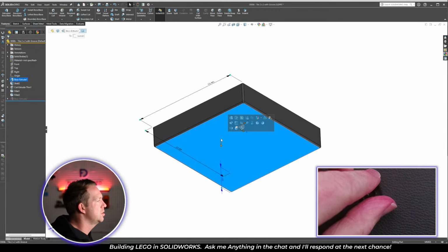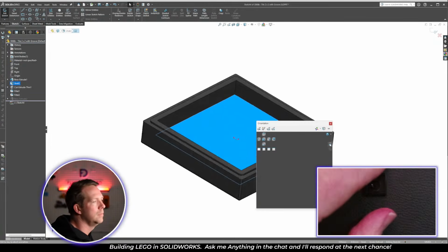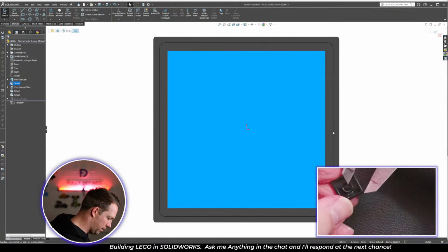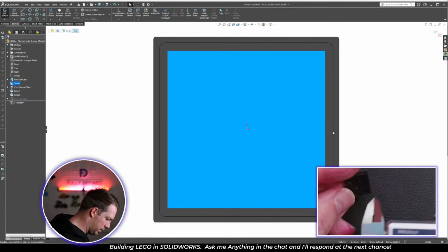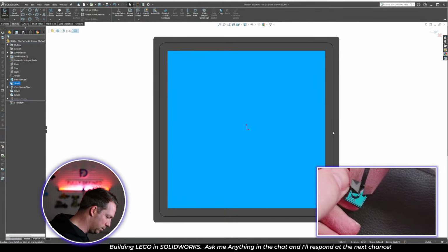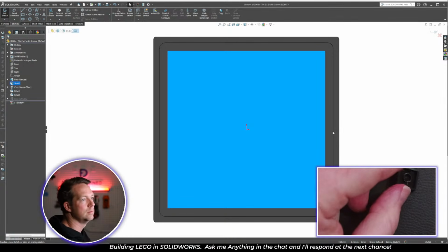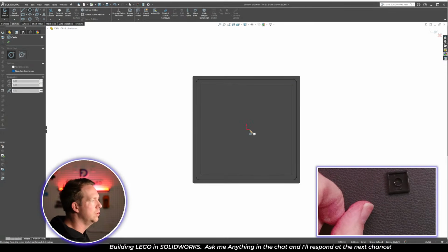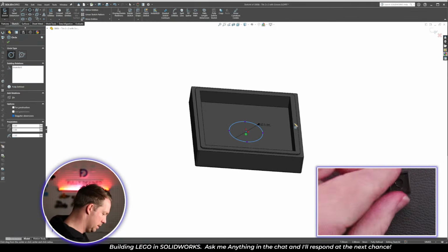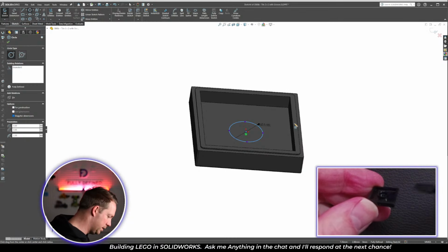So we can sketch on either face. Let's sketch on this face. And this should be something that we can dimension or measure pretty easily. So let's go inside of the circle. It's 5, and then thickness of the circle, 0.8. So we'll do just one circle of 5, and then the height of that detail pretty much goes to this top surface.